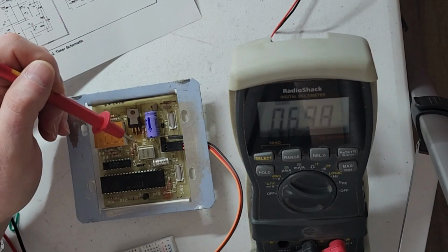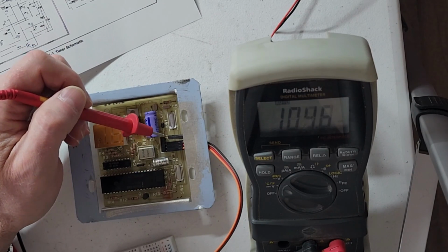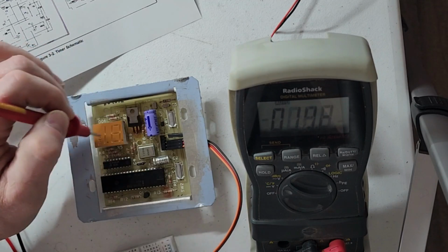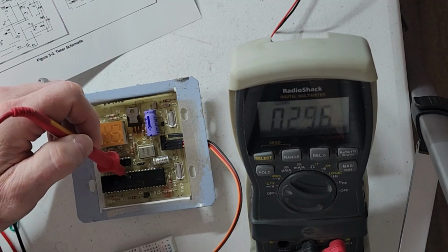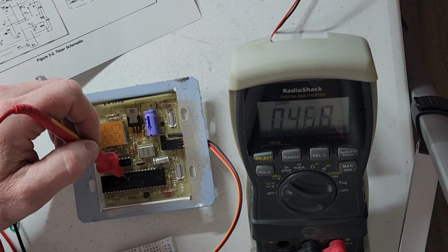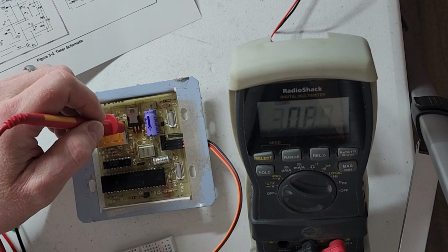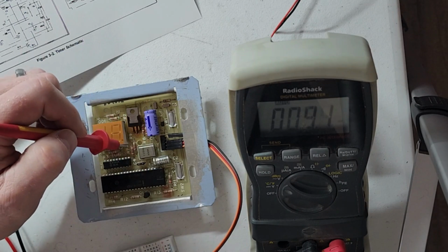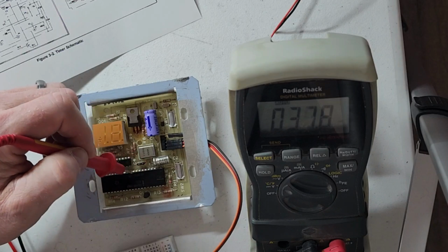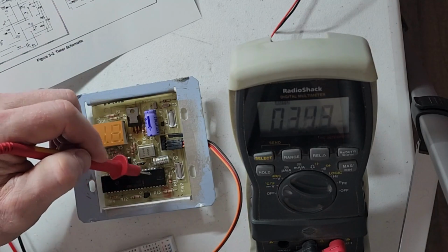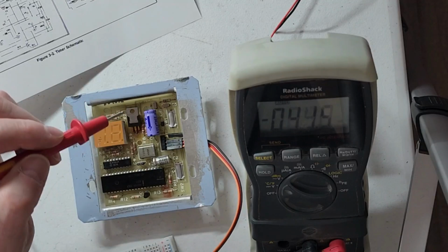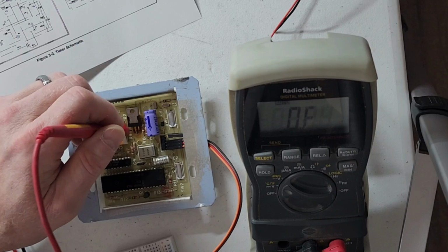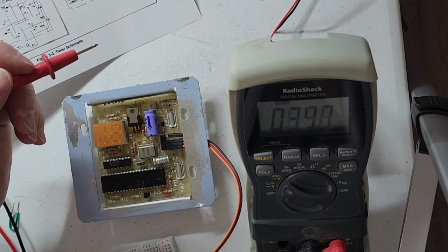I would have to clean that voltage up first. Well, maybe I could use this board in conjunction with an Arduino, pull this chip out, and supply the 5 volts to the Arduino from here. I could probably do that, especially if I got not an Uno board, but a Nano, one of those little Nano. However, they run on 3.3 volts. But I could take his 5 volts probably and just make a simple voltage divider with it.